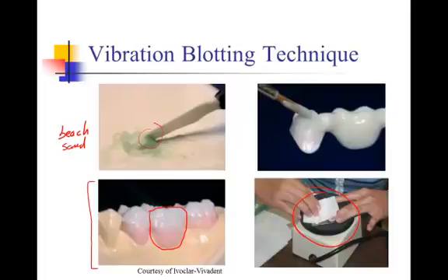The pink part does not remain pink after it's fired in the furnace. The white part will not be so opaque white. It'll turn more translucent. The colors are color-coded for the degree of opacity that the different types of ceramic material will have after they are sintered and become a white body. And they're colored with food dye type chemicals that burn off in the furnace or decompose to lose their color.